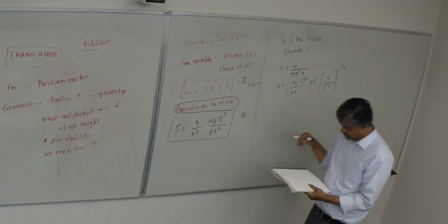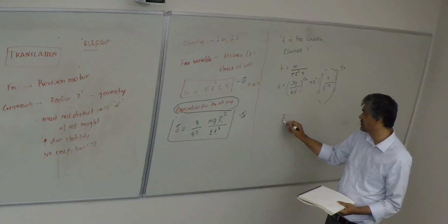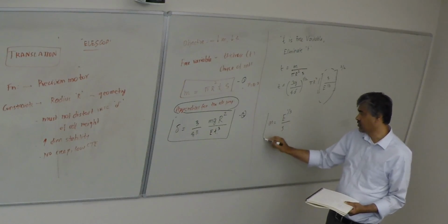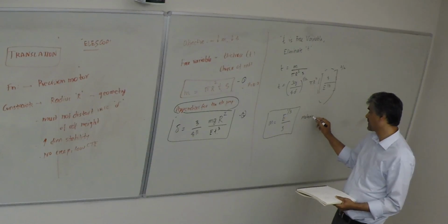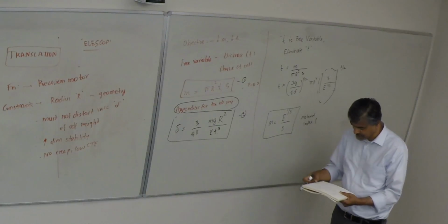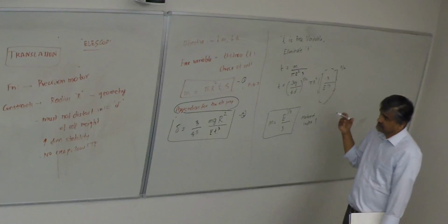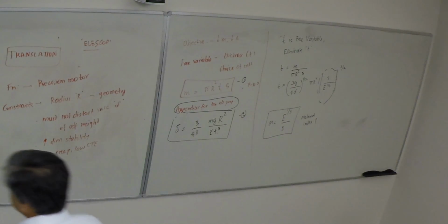So from all this, you are focused on this index here, which is E to the 1/3 by rho. You have seen this before for a plate. This is your material index that you are trying to maximize for the plate. And then there are other attributes, of course, that are more qualitative in nature, right?